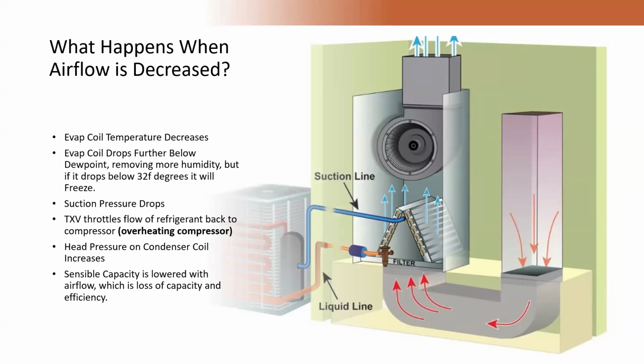All we're doing is it's speed, it's mass, it's energy. We're moving energy in and out of the home with airflow, and we're moving energy in and out of our condenser with refrigerant. If we slow that down on either parameter, so does our capacity. We might as well turn them both off. Stop moving refrigerant, stop moving airflow, you stop having sensible capacity in operation.